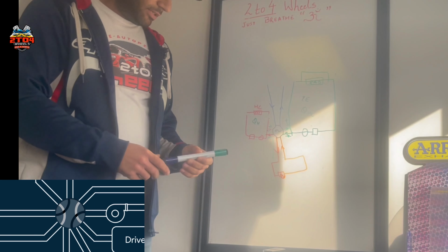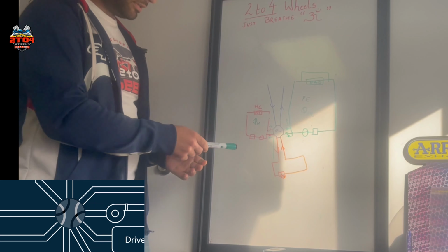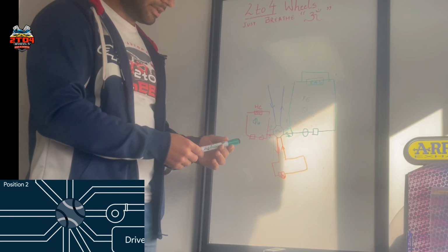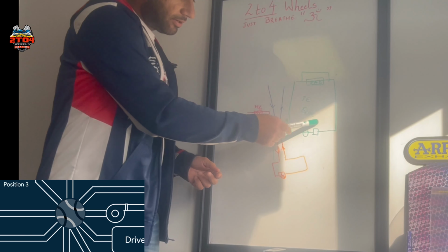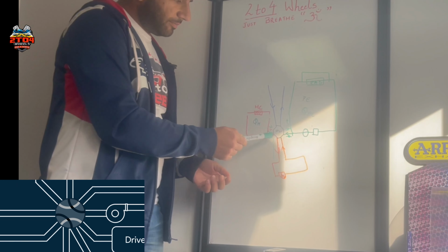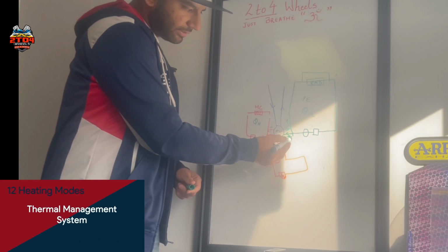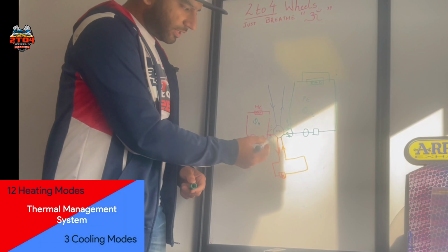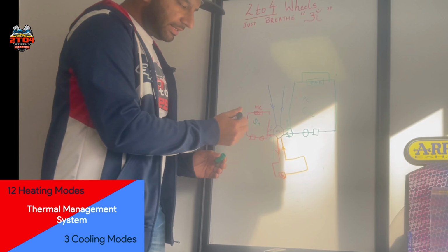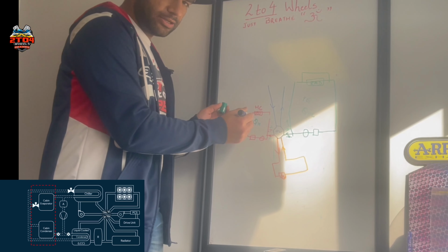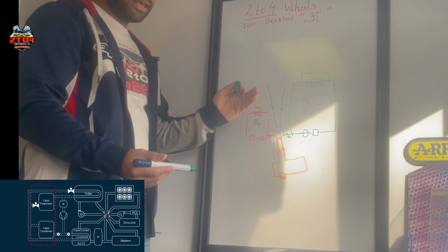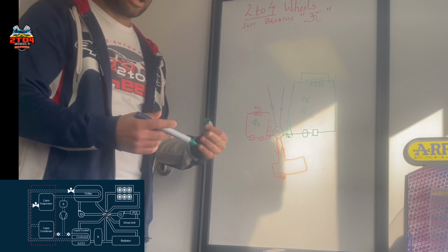So how the Octovalve works, it's one valve that actually monitors the flow from everywhere. Basically, we have to do a heat and mass transfer. Let's say now this power electronics loop has enough energy, QPE, to heat the cabin. So the Octovalve will start the flow from power electronics and take that flow to the cabin, and whatever rejected heat is left in the coolant goes back into the power electronics loop. We cannot segregate the two loops once the Octovalve is open.